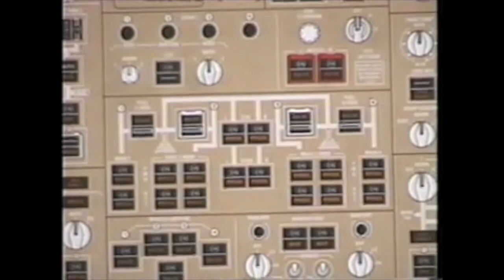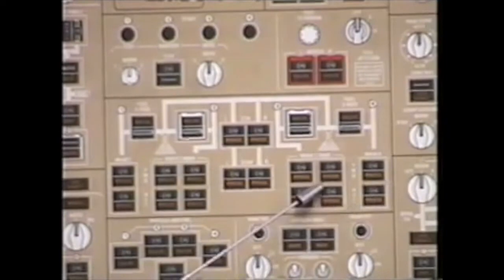Moving all the way over to the right is a fuel transfer main tanks 1 and 4 switch, primarily a maintenance switch. This switch, when pressed, opens transfer valves between main tanks. Pressing that switch allows gravity transfer between main tanks 4 into 3 and 1 into 2. Maintenance uses that switch to defuel your airplane to get the fuel out of the outboard main tanks. The only time the flight crews will ever use this switch is per an irregular procedure, such as 2 boost pumps inop in an outboard main tank.